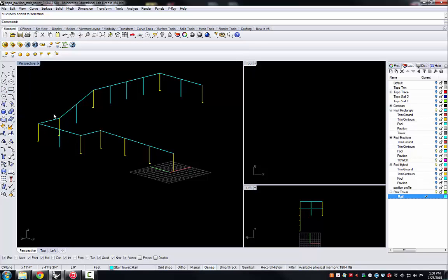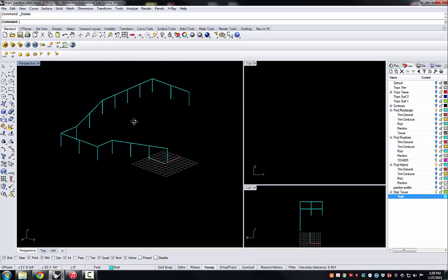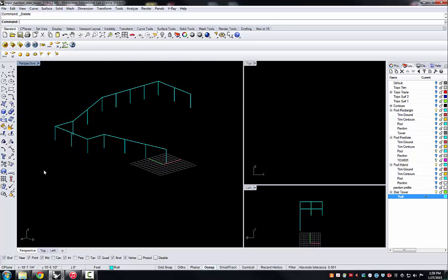And I'm going to ungroup them, Control-Shift-G, so that they are ungrouped. And I'm going to come in and actually delete the squares that are at the bottom of them, because we don't want those to be thickened up into the kind of pipe rail that we're going to be using for the handrail itself. And I can now also take all of this wireframe geometry and select all of it and join it together.